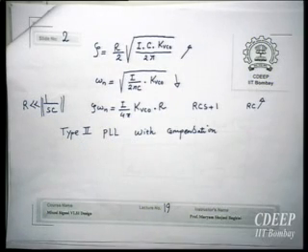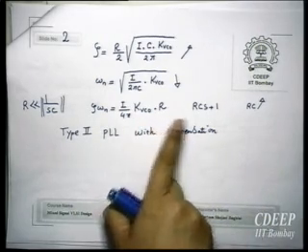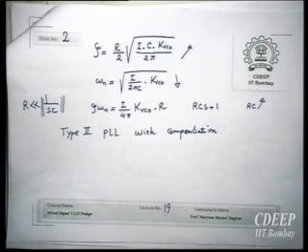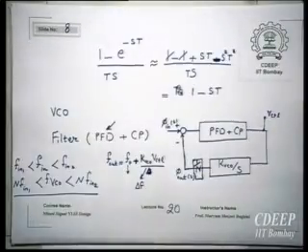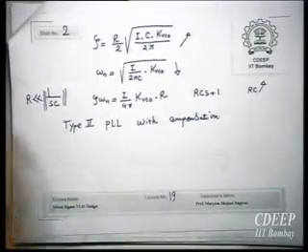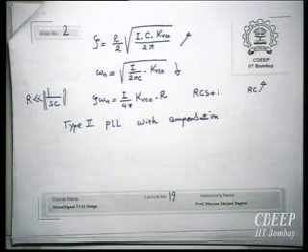Now I come back to the VCO. That also will add 1 constraint. Now I have 3 constraints and 4 values. That is also good. And then I can see if anything else can limit my performance. Otherwise, I will try to add power. Therefore, I will have 4 constraints, 4 parameters. Then it will be designed, meaning that it will have only 1 solution.